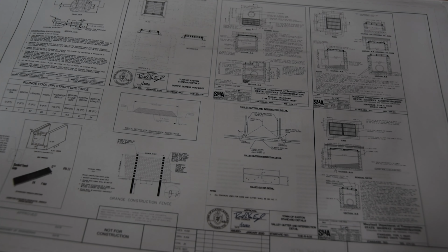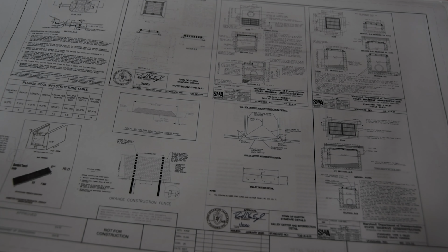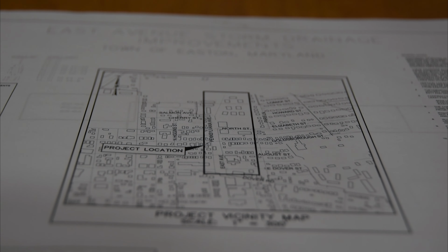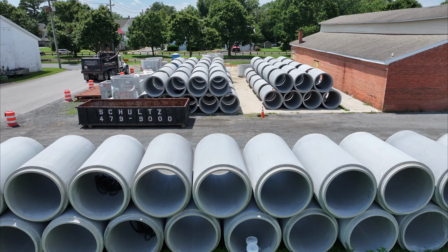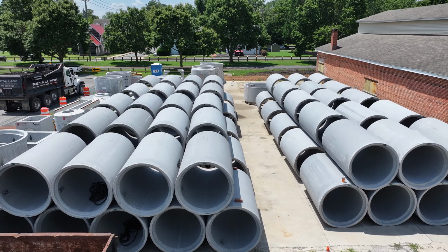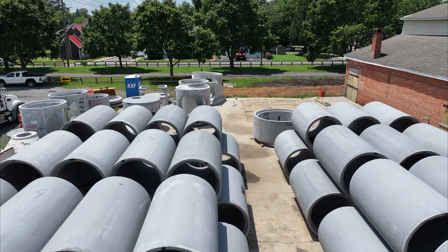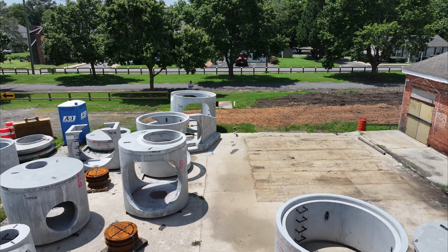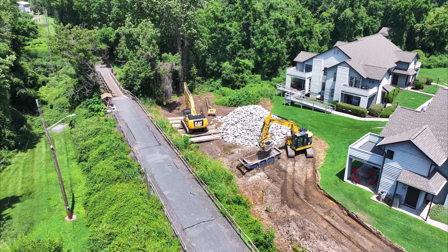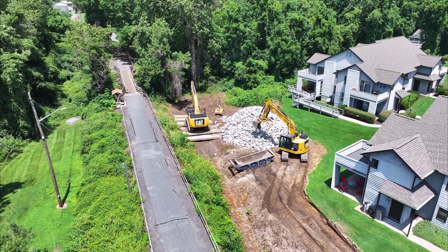At each of these milestones, review and input was provided by the town of Easton and Easton Utilities. After a design period of a little over a year, final plans were signed. The resulting design included a new linear stormwater pipe system that included 2,100 feet of new or upsized storm drain piping, 10 new manholes, 7 new inlets, 1 new head wall, and 1 plunge pool with the capacity to handle 10-year and larger storm events.